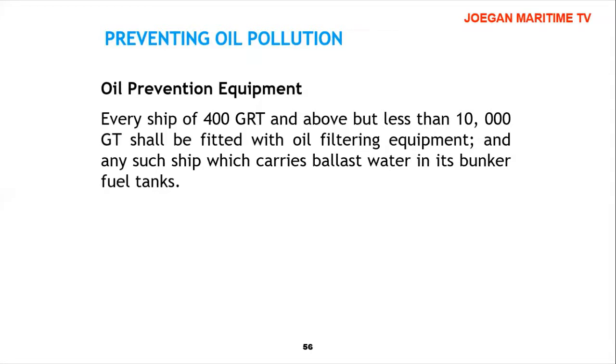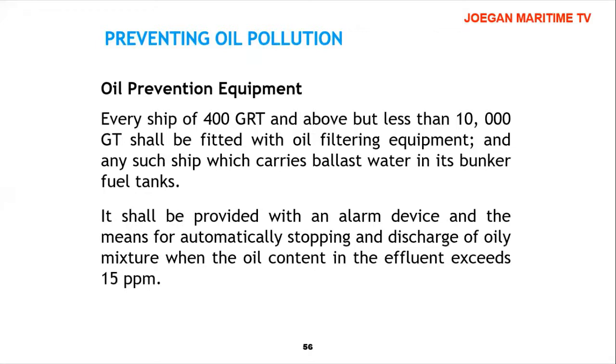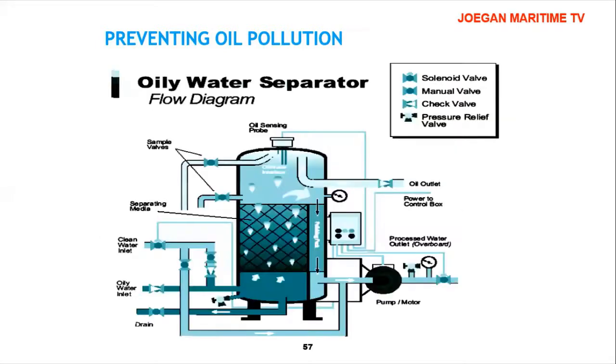Every ship of 400 gross tons and above, but less than 10,000 gross tons, shall be fitted with oil filtering equipment, and any such ship which carries ballast water in its bunker fuel tank. This is an example of an oily water separator with alarms.